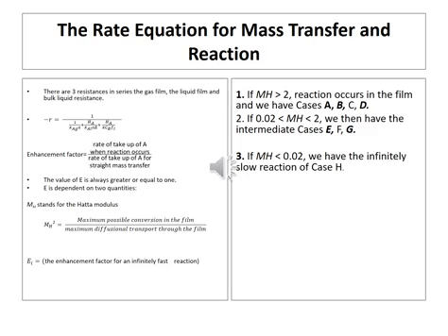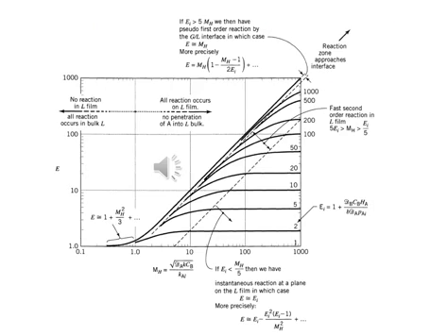Depending on the value of the Hatta number, we can know in which of the 8 cases our reaction is. If the Hatta number is greater than 2, then these become the ABCD cases. If the Hatta number is in between 0.02 and 2, this becomes the EFG case. And if the Hatta number is less than 0.02, this becomes case H. The Hatta number and the instantaneous fast reaction enhancement factor are summarized in this graph.